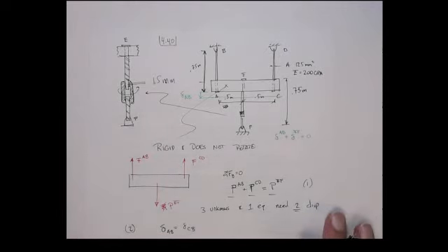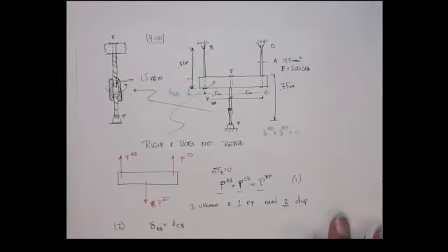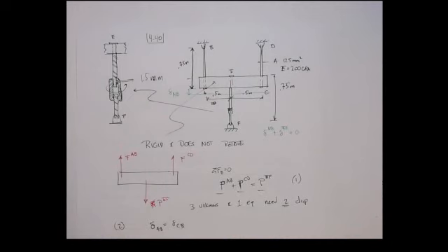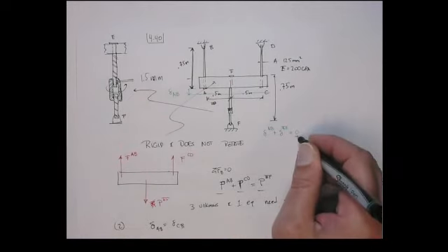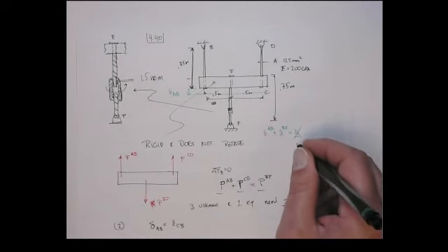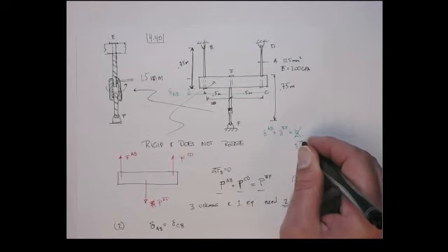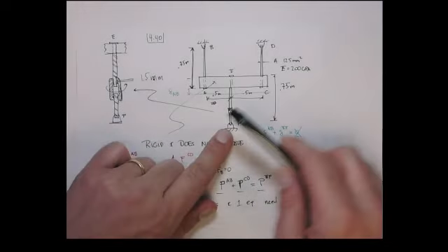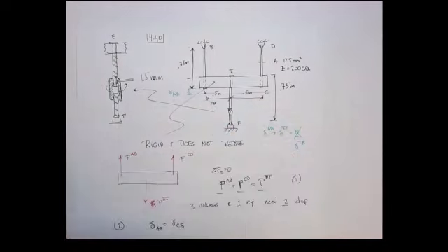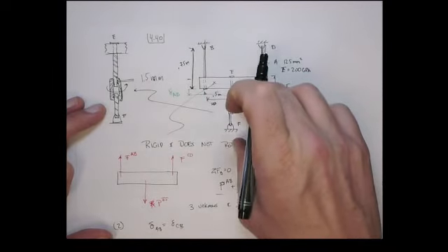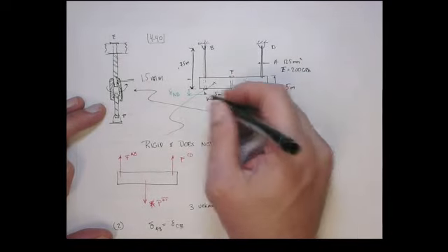Well, in this situation, we have the turnbuckle. So actually what happens is this distance here is not going to be 0. It actually has to become the amount of change in the turnbuckle. So forget there's a turnbuckle. Imagine instead of a turnbuckle, there was somebody just pulling this down a little bit, right? So here's the delta AB.